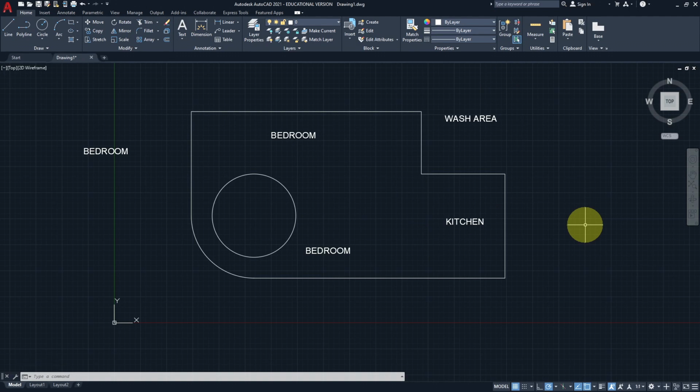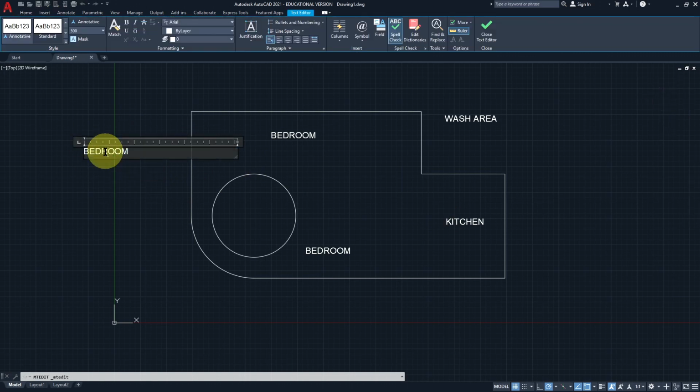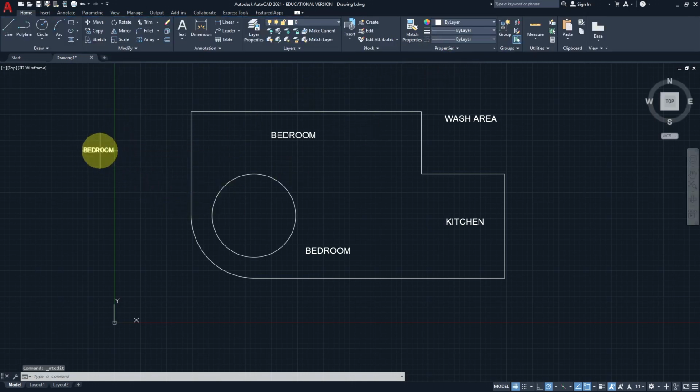If you're not satisfied with the font size, so that it's uniform, on your original before you copy it, set the font size that is appropriate for you, because there is no exact standard for size as long as it's visible. For example, if the font is too big, you can adjust it to 200, enter, then check, then use this to copy to any other location in the floor plan.